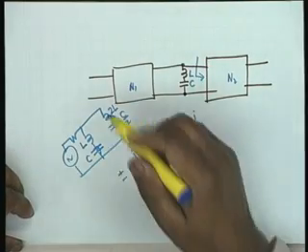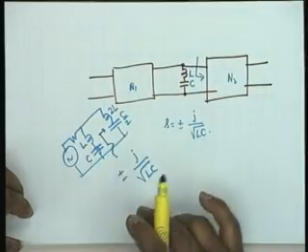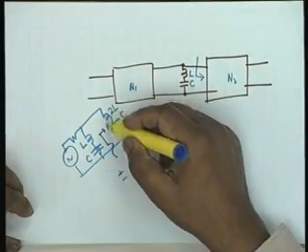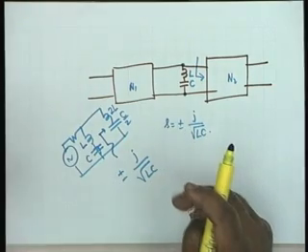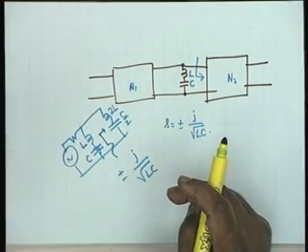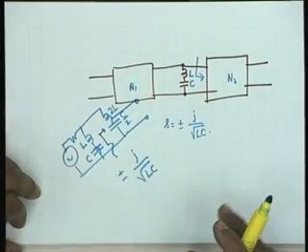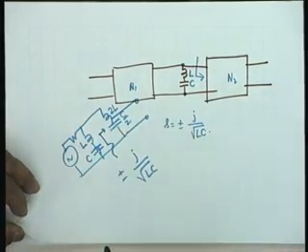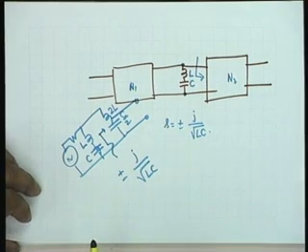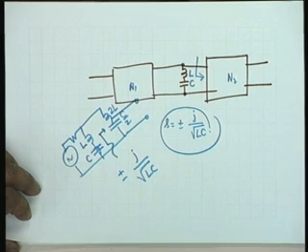But if by looking into the right, you have a pair of zeros at the same frequency, then obviously this is not a zero of transmission. That is, if you measure the voltage across C by 2, for example, you will get a voltage. Why? Because there occurs a division of current between two short circuits at the frequency S equal to plus minus J by root LC. Is the point clear? Okay.